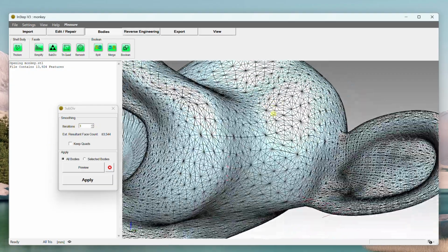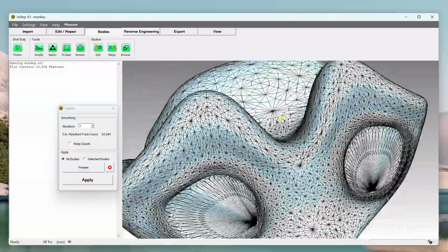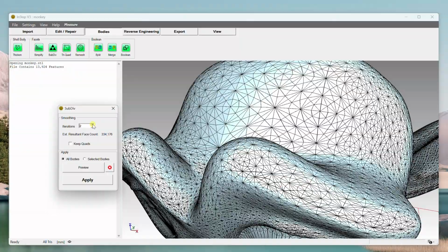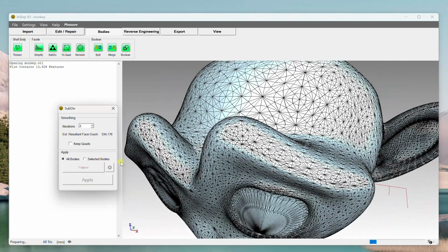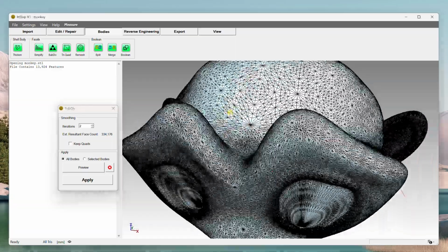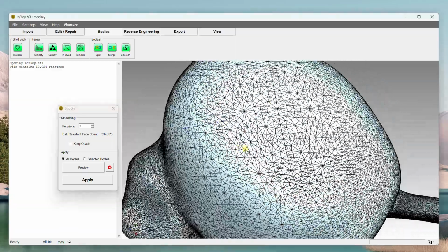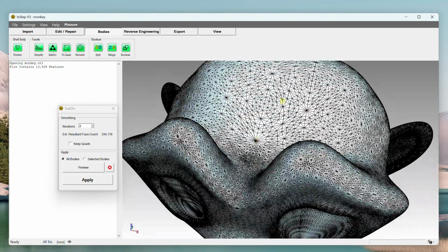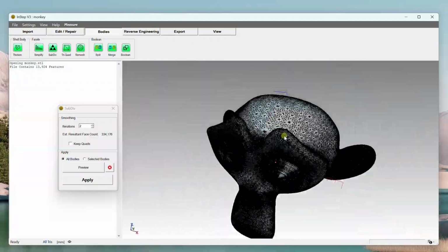But you see the overall body is actually smoothed out now, so some of these rougher features have become a lot smoother. And if we take it one further, so now we have 334,000 facets. Again, this will take a second. We now see this body, and really what it does, it just takes each original triangle and looks at the normals at all of the corner vertices and tries to create a more uniform division of that.